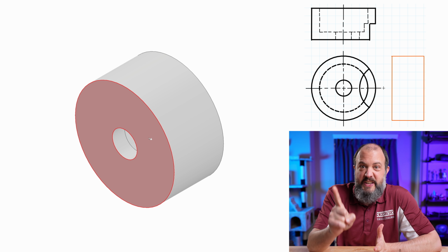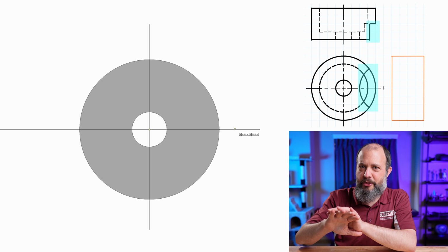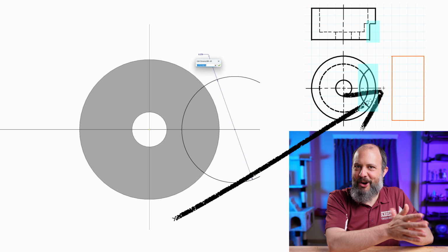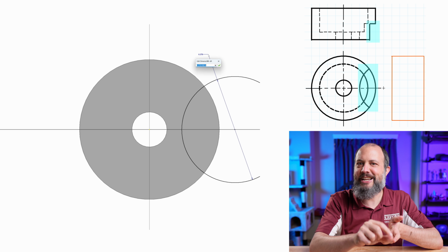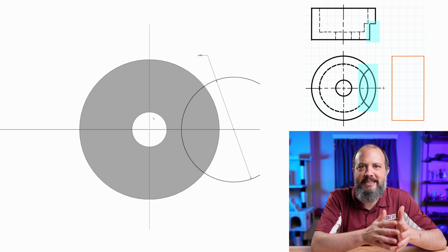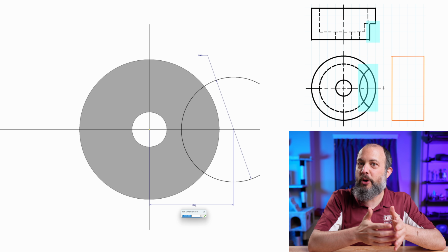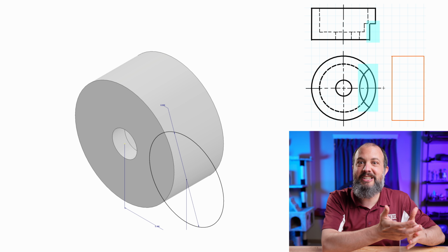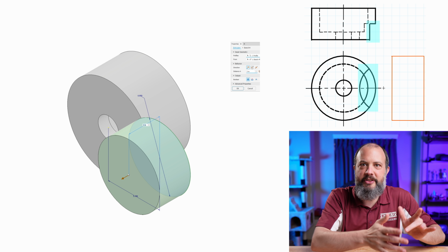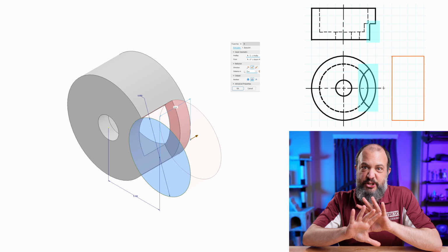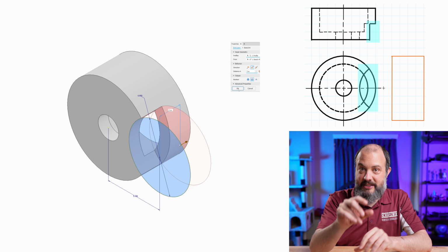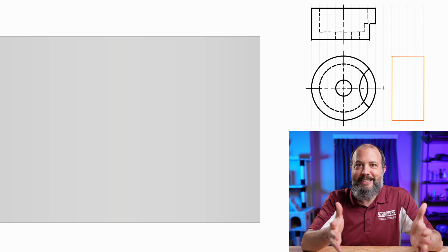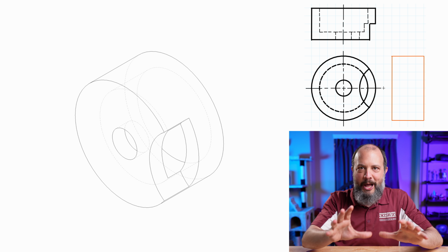And there's only actually one feature left, which is that circular cutout over on the right-hand side. On the front view, this little plus out in sort of the middle of nowhere off on the side of the drawing, that represents the center of the circular cutout over on that side. Right? That little plus has to be there because if you wanted to dimension this drawing, to actually put numbers to it, you would need a point to measure to, and that's always the center of the circle, is where you reference all the dimensions. I draw a circular shape, extrude it part of the way inward, and I can use the top view, that sort of cutout, to see how far in this cut goes. And that was it. It was just one cylinder with these 3 round cutouts.